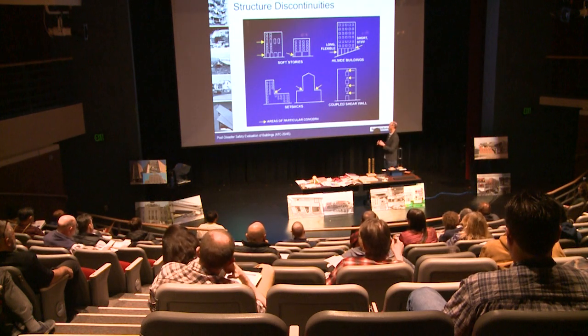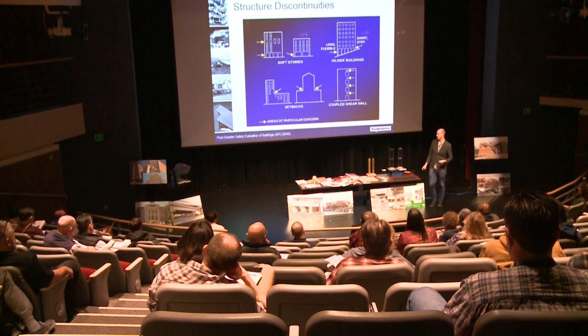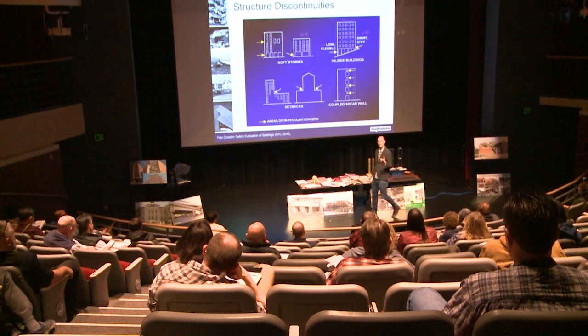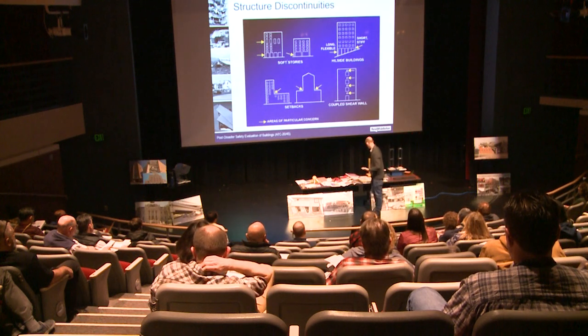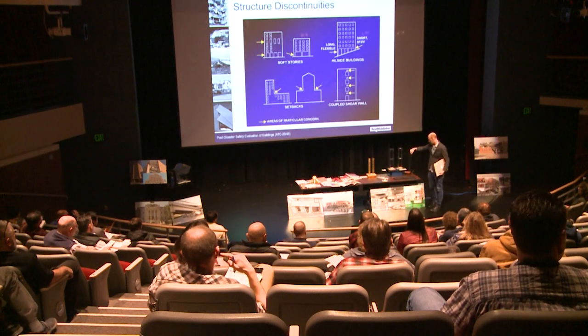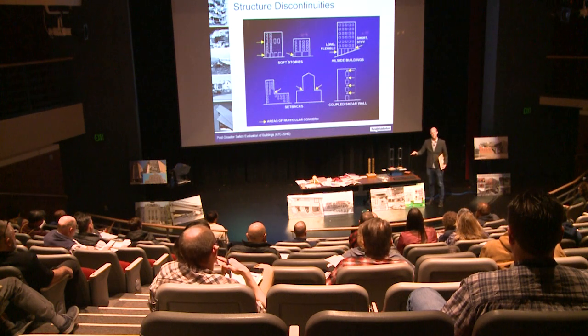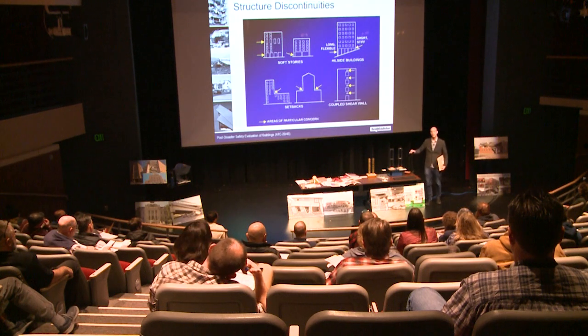So if there is an earthquake for this hillside building, everything else being equal, where do you expect to see the most damage? The short or the tall ones? The short, which is maybe counterintuitive to some, because when we think about gravity, let me grab this guy, from a vertical standpoint, the short columns are way less vulnerable to gravity load. Here's that buckling of the spaghetti that Rami was talking about earlier, than the long columns. But from a lateral standpoint, of course this one's barely even attached, but the stiffness is dramatically less.